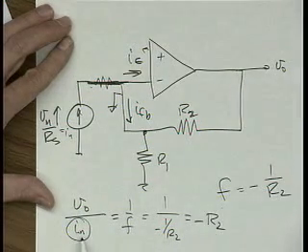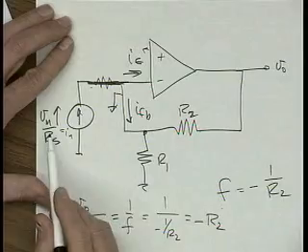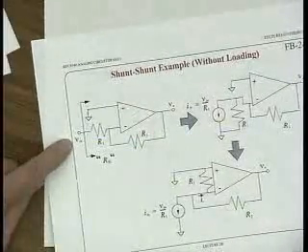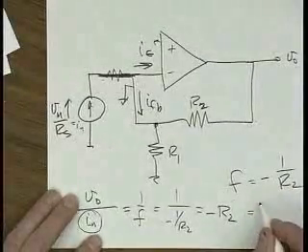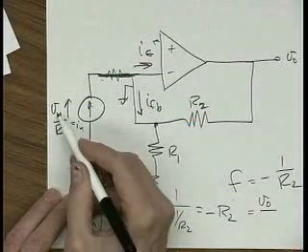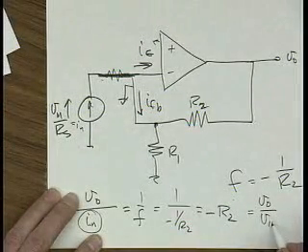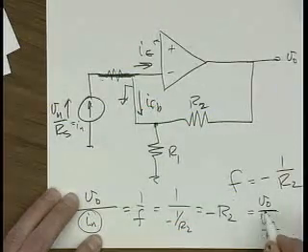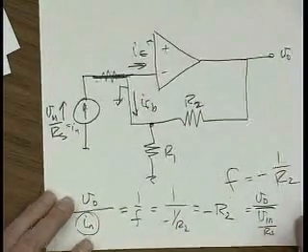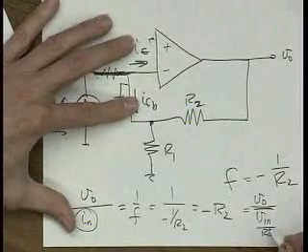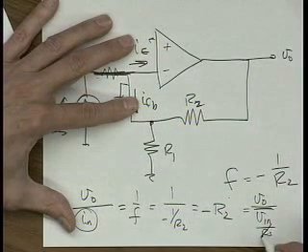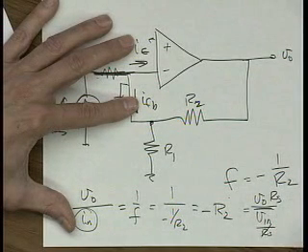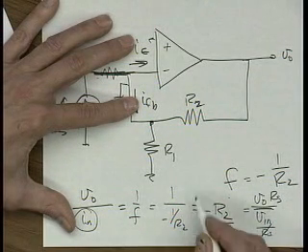But now let's take I in and replace, let's say what I really want to do is look at V out over V in, because that's kind of the problem I initially asked for here, V out over V in. So I let V out over I in equal V in over RS. Right? So you can see that if I take RS, I can bring that up into the numerator from there.